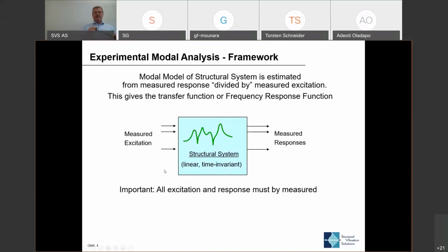This hammer here, we have a force transducer sitting here that actually measures the force that we are supplying. This is one way of impacting or exciting a structure with a known excitation. Besides that, we then have to mount some sensors, typically accelerometers, on the structure that can actually measure the response in one or more points during this test.